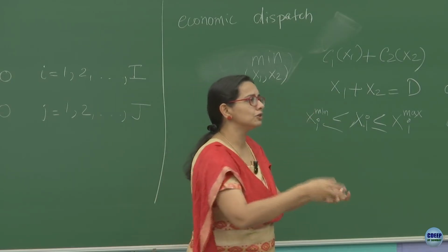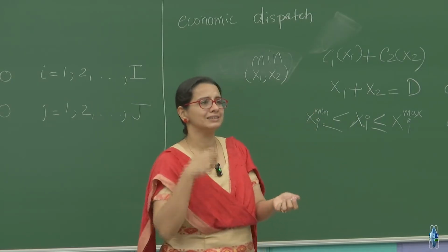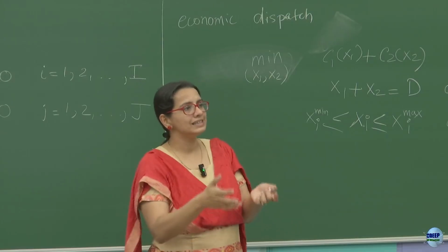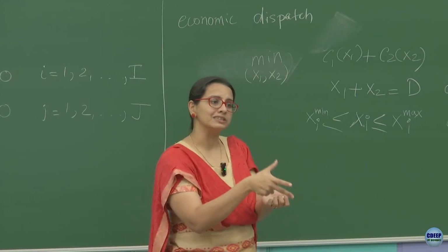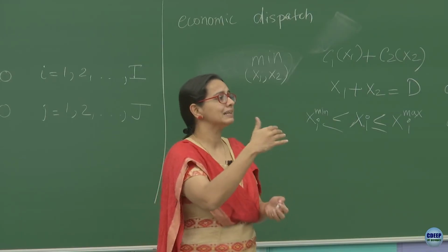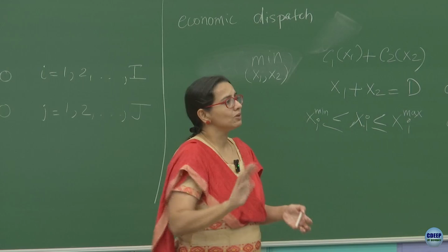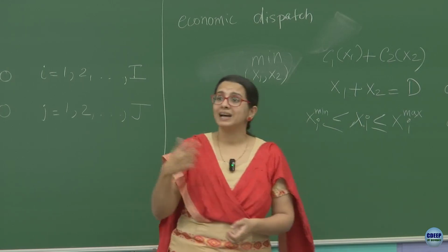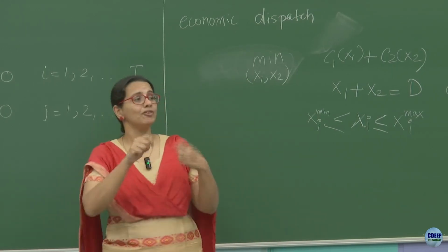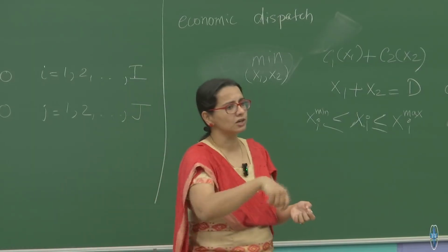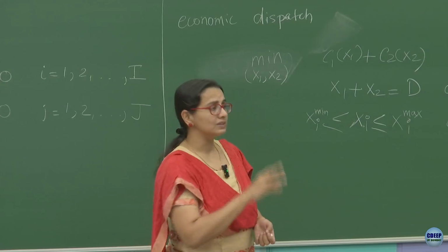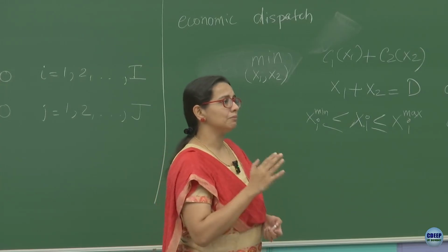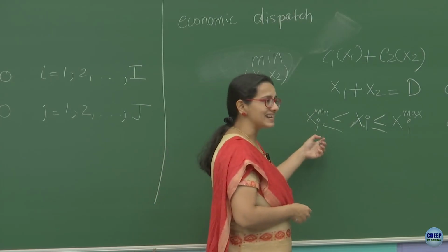The amount of fuel you burn for the amount of output you get is at such poor energy efficiency that the range between 0 and 100 is not an economically viable range. And so there might be a technical minimum on it, nothing below 100. There could be other reasons where the generator may be physically incapable of producing anything below 100 megawatts. All right. So all of this, economic minimum, technical minimum, together we may decide what this X1 min is going to be.